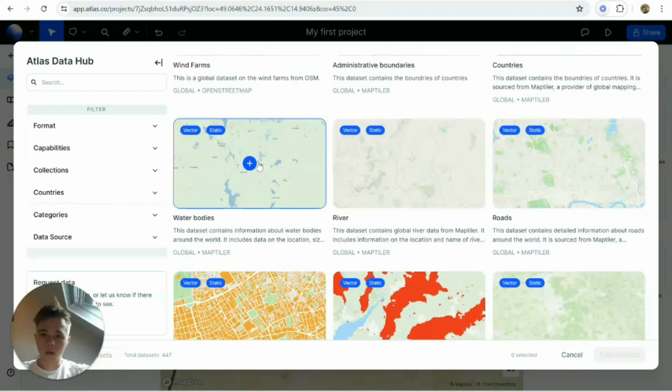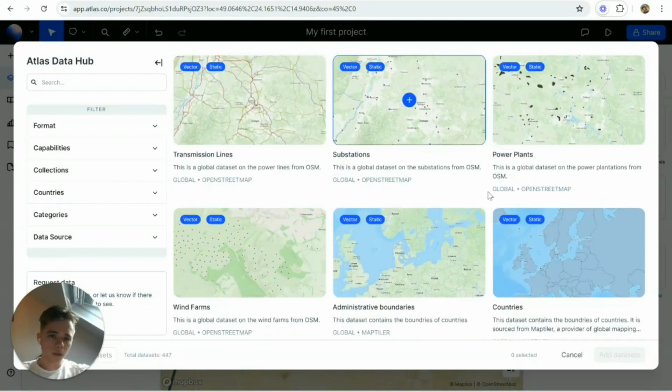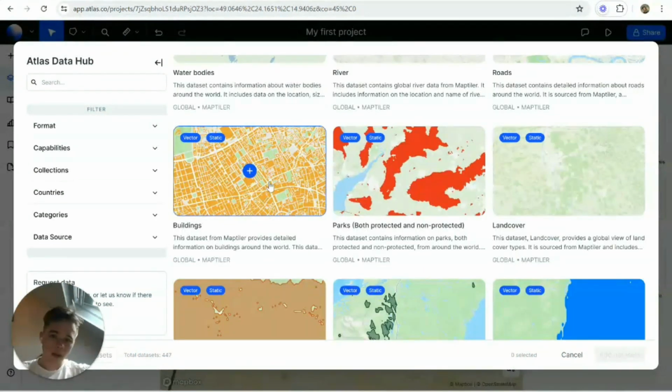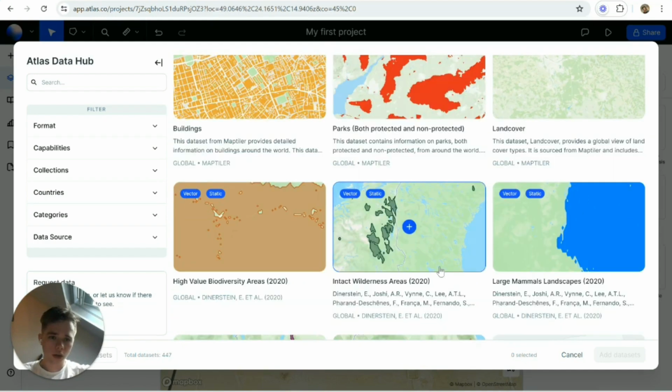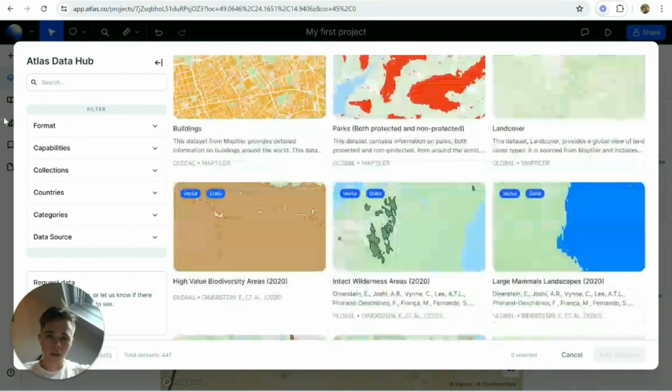And there's much more data that you could use, like roads. You won't put solar panels on roads or maybe on buildings, but if we are looking at just farms right now, then that may not be relevant. However, you could even run another analysis on the buildings to find the suitability of solar panels on buildings as well. Either way, I would suggest you use this land cover, the parks, the buildings layer, and the existing solar farms layer as well, and then try to find potential locations from there.